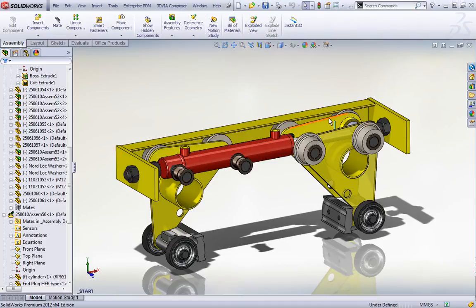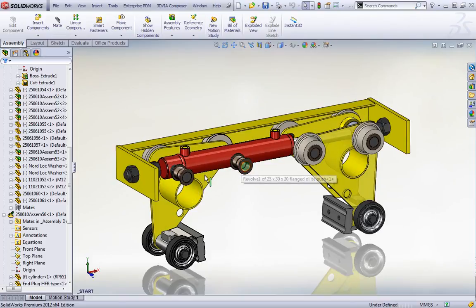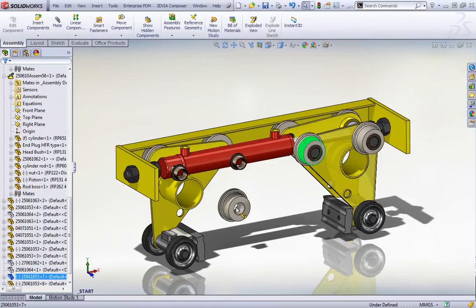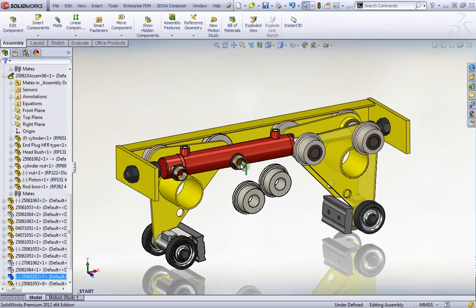The Alt key here. Some of you might have used the Alt key already or not. Alt essentially is a great way of smart mating. So I'm going to do a control drag to make a couple of copies of these parts. Let's go and bring the pins back there. Want those pins showing back up.